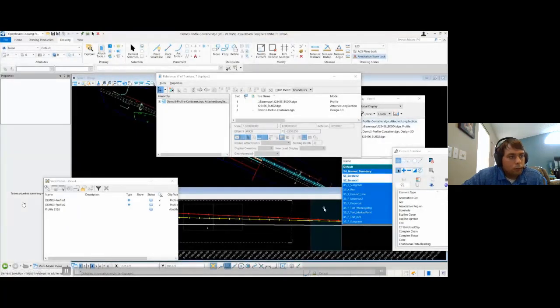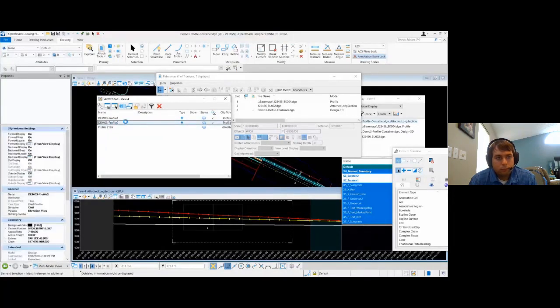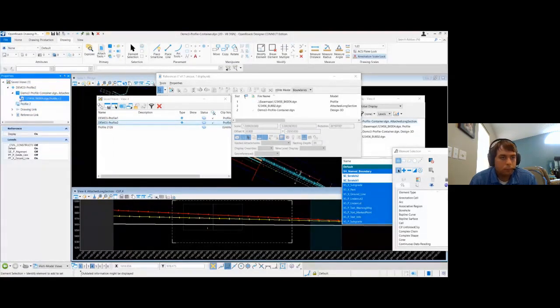Your profile drawing models also start off with the save view, just like your plan view, but it is slightly different. So if I take a look at my saved views, I'll notice that when I go to control the level display, I only see one of the nested references. So all the references from the 3D cut and the attach all profile views are not showing up here. So it's not really a great way to control level display if you can only get one piece of it.